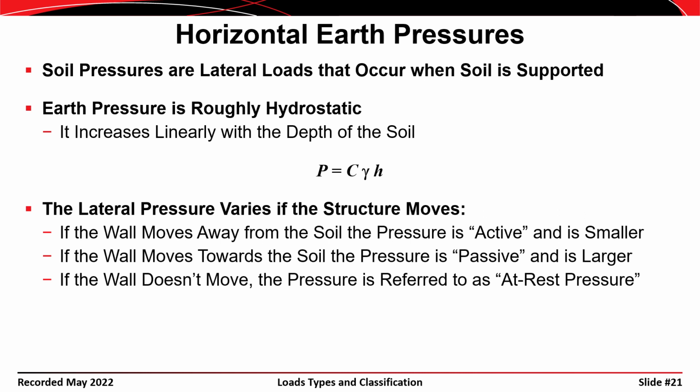Okay, horizontal earth pressures are another force that we have to deal with in structures, and if you look at the pressures due to earth, it's roughly hydrostatic as well. So it's equal to some constant times the self-weight of the material, or the density of the material, gamma, times the height of the fill, h.